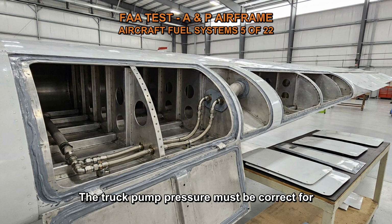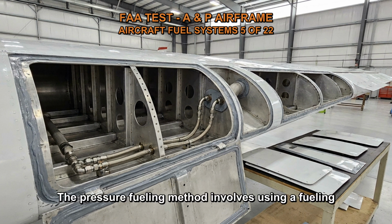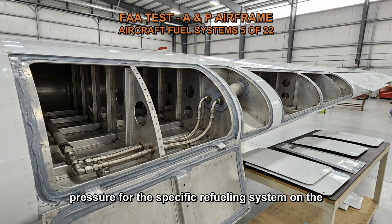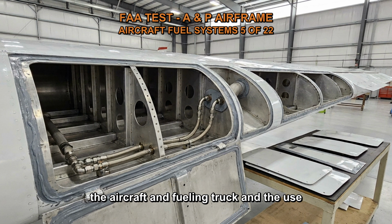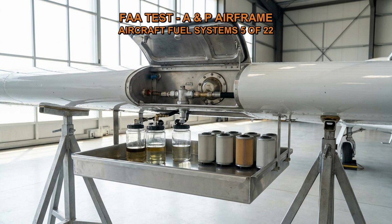The truck pump pressure must be correct for that refueling system. The pressure fueling method involves using a fueling truck to pump fuel into the aircraft's tanks at a high pressure, typically around 50 psi. It is important that the pressure of the fueling truck's pump is set to the correct pressure for the specific refueling system on the aircraft to avoid over-pressurizing the fuel tanks and causing damage. Additionally, other precautions such as proper grounding of the aircraft and fueling truck and the use of appropriate hoses and nozzles should also be observed.